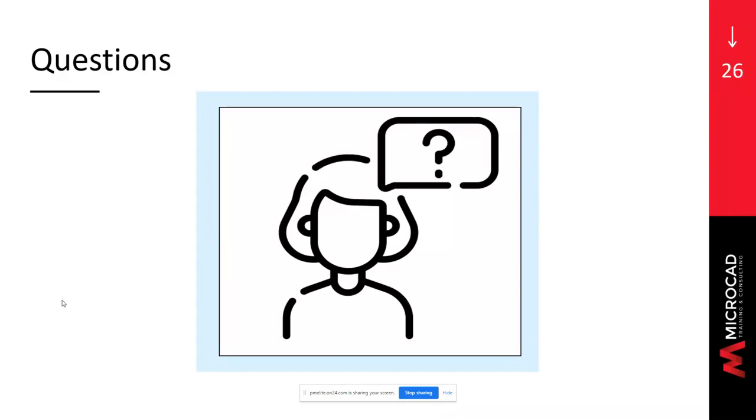Built into Revit, there's a lot of integration. So things like the publishing process I talked about is done from within the Revit application itself. If you're using AutoCAD, you would need to do that process manually outside of AutoCAD. But the other processes, the sharing and the consuming, those are doable with AutoCAD just the same as it would be with Revit.